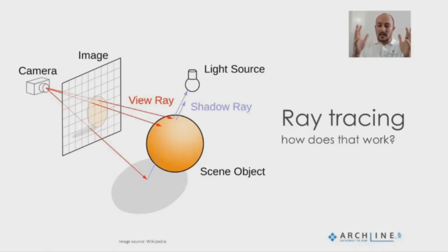And using this kind of filter that we have in front of us in a certain resolution, we see the virtual world. While I'm talking about it as a renderer, I'm imagining myself as the renderer, so I'm seeing the world through these tiny dots, and I'm shooting rays to the world and seeing what it hits, whether it hits a scene object, the building itself, my desk, which I represented in my interior, or the sunlight itself. So this is how the renderer works.